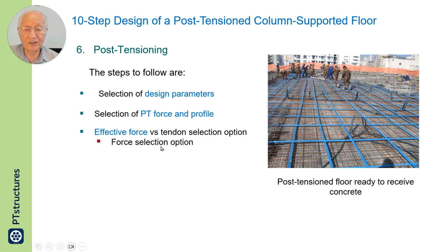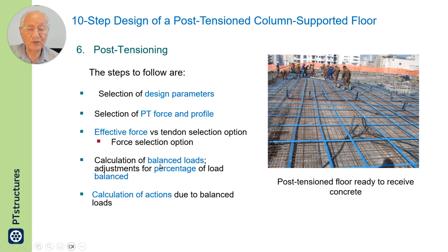But for hand calculation, we will not do so. We assume a force uniform along the member. When it comes to method of design, there are 3 methods explained in another presentation of this series. But the common practice, almost universal practice, is to use the load balancing method.